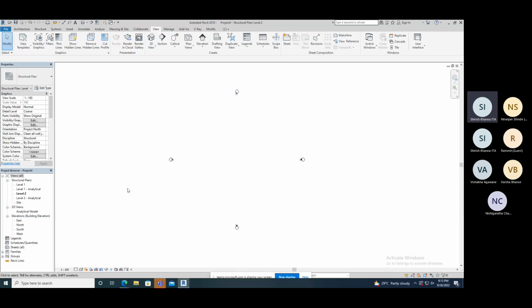Okay. Now, the first thing when we are going to start our Revit is you need to create the levels first. Suppose we have a 5-story building, so we need at least 5 levels there. Or one basement is there also, so footings we need to create. So everything, we need to create the levels first. I hope the levels are clear to you. You are from a civil background. I think the levels are clear to you now. What is the plinth height, plinth level?